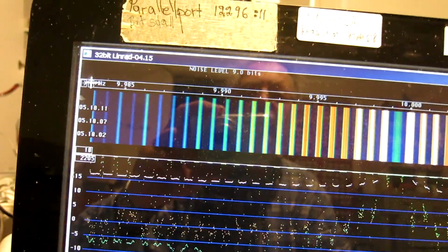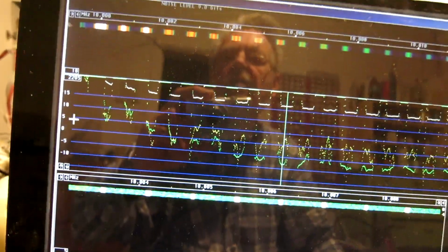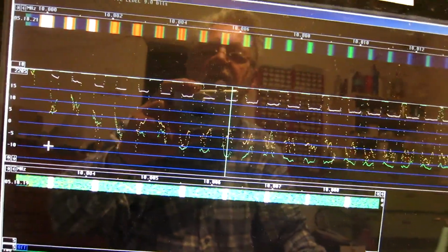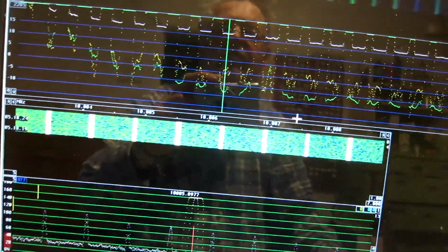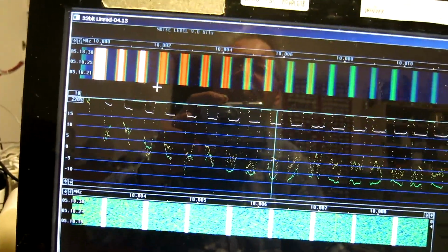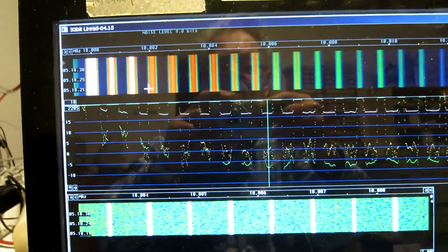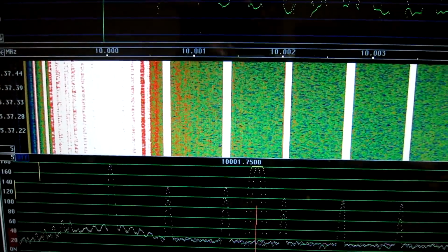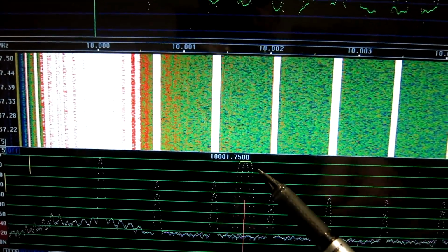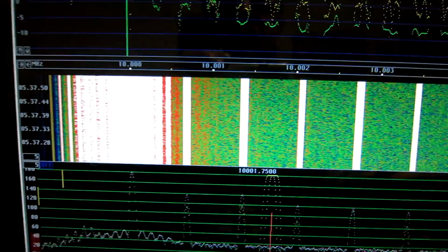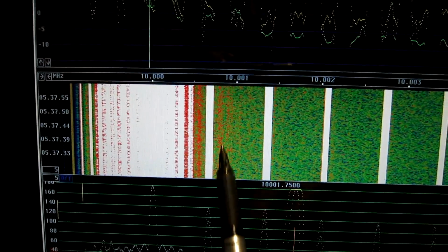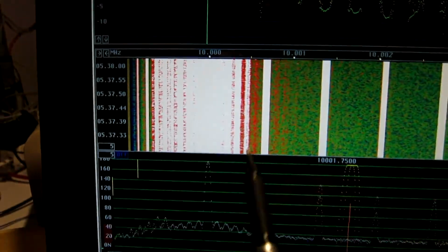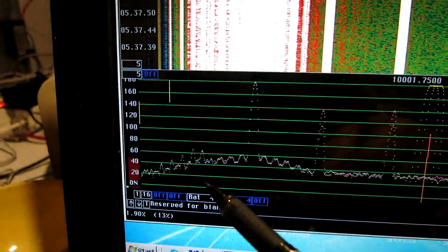But I can expand it this way also. And now I can see much easier what the green trace is. And I will evaluate the noise at closer spacings. I cannot go closer than this gap at 1.75 kilohertz, because at closer separations there are these aliasing spurs, and they are much stronger, even closer, and you can see it here in the spectrum.